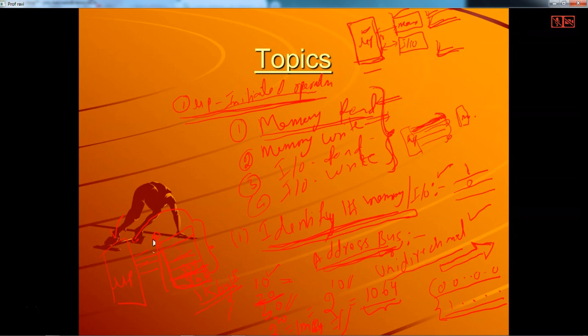Now we are discussing the significance of the address bus. The significance of the address bus is that the memory accessing capacity of a processor depends upon the number of address lines you have. So the memory which you can connect to a particular processor is limited by this. Take your mobile phone: you can connect 8 GB, extendable is what we say, but you cannot connect 1 TB.